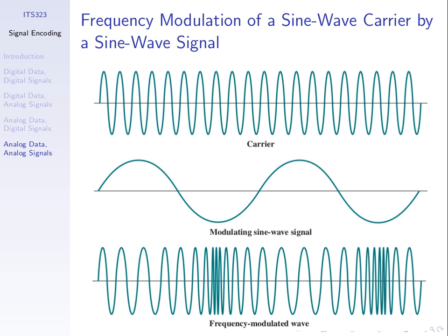So the voice is transmitted using, what was it using then? I think it was using FM in that case, frequency modulation, to transmit that voice from the wireless transmitter to the receiver at a much higher frequency. And then it's converted back down to the original frequency when it's passed up until the speakers and then down to your ears.